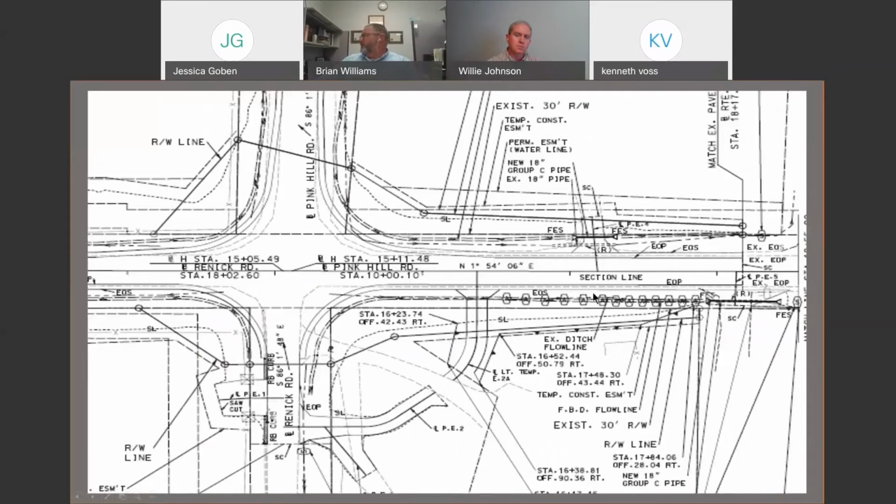As you can see, we've got curb and gutter shown going in on this side. We've got a new pipe over here. We've got these entrances being constructed over here. So we've got ditch checks here. But again, keep in mind what the permit requires. The permit requires all perimeter controls go in prior to any land disturbance activities.